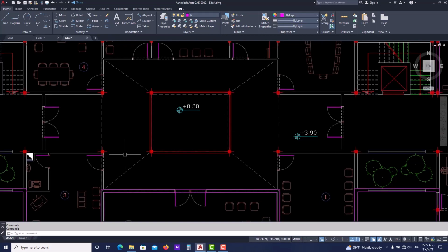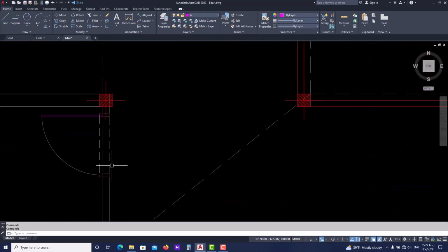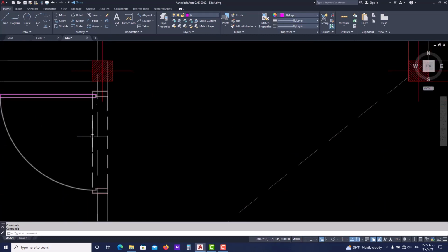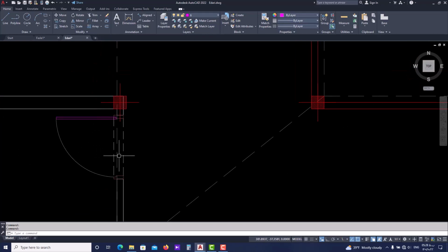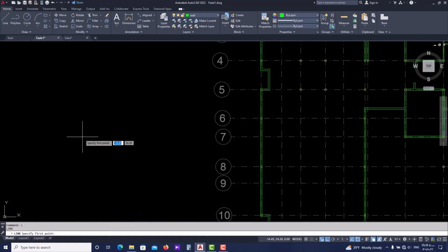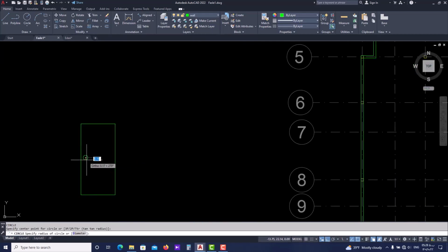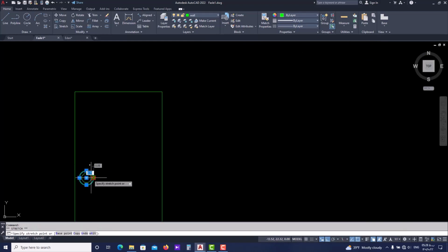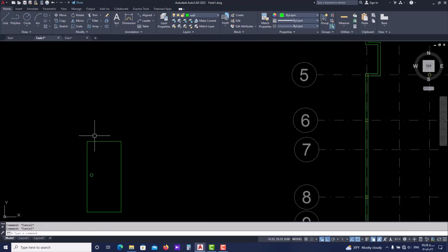First of all, we have these dashed lines here. Guys, when we have these dashed lines in our plan, for example, in door openings, it means that we have some kind of a height difference in their bases, or we have something like a dome. As an example, again here in our file, let's assume that this rectangle is our door. Alright, the script got a little bit large. Above the door, we might have something like an arc or dome, which we show with dash lines like this.